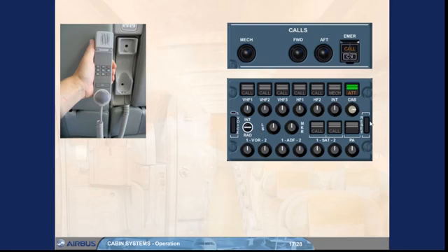You can speak using a push-to-talk push button. This will automatically stop the flashing lights on the call panel and the audio control panels. When the conversation is over, the call will be reset by pushing the reset key on the cabin handset or by replacing the handset. We will now continue with the oxygen system and the protective breathing equipment operation.